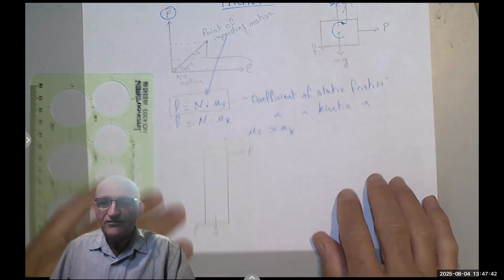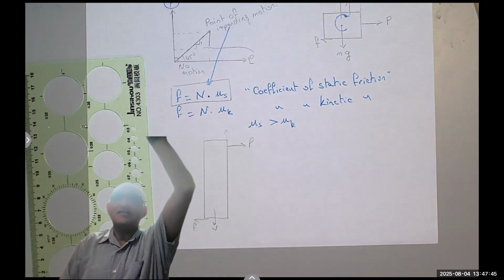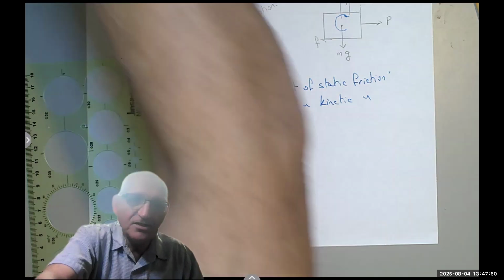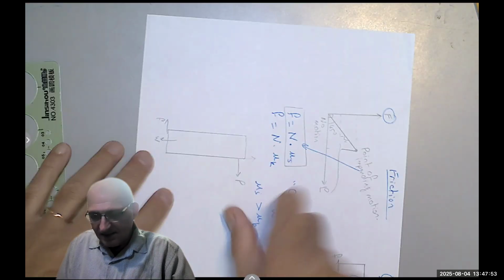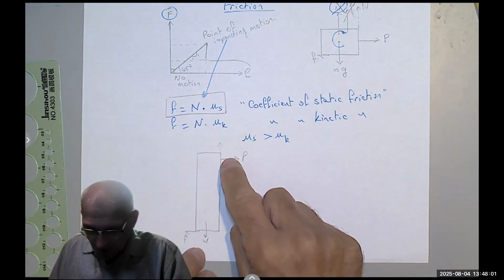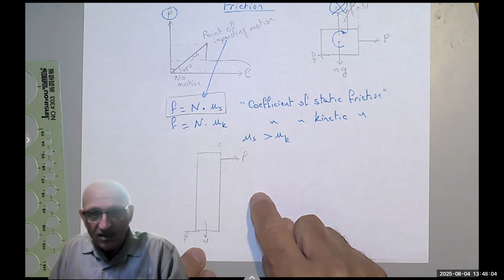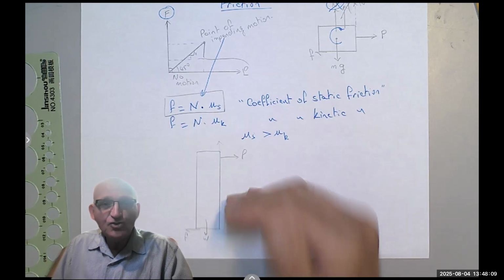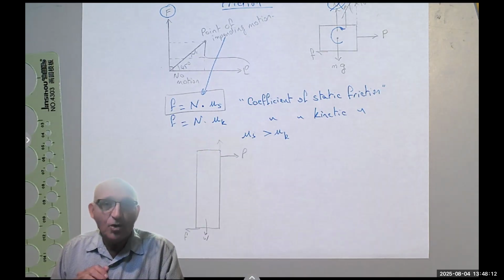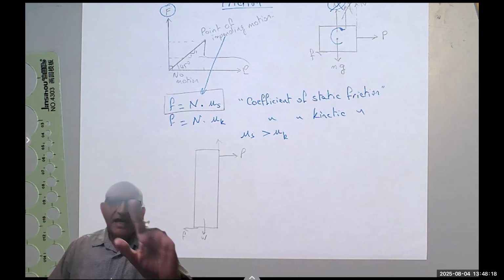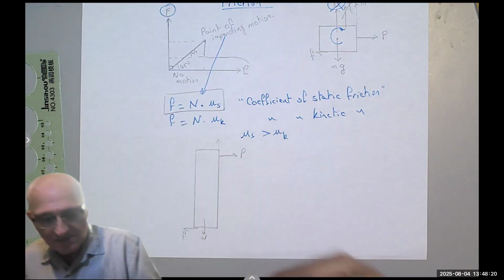Even intuitively, if you are trying to push a heavy box that is slender and tall, either you move it so that this would be the width and that would be the height. And now, even though you had to scoot, you can move it. Or instinctively you'd go down and pull it from down here. You go down to reduce the tipping moment, so that the restoring moment can resist that. Anyway, that's the whole story really that we need.